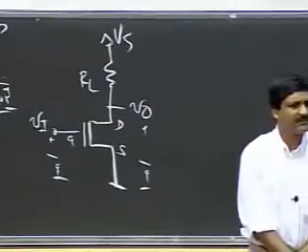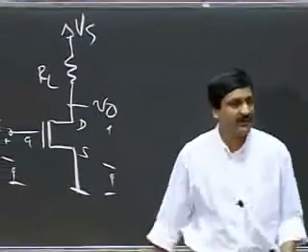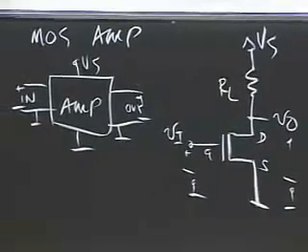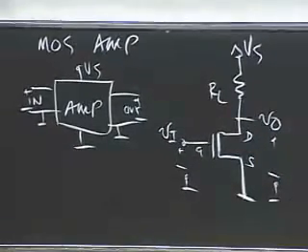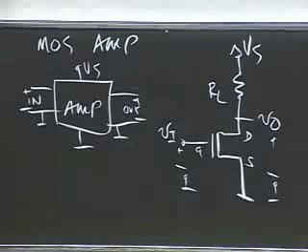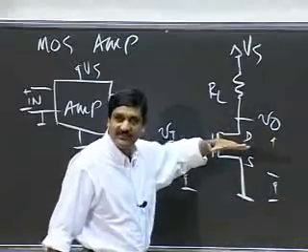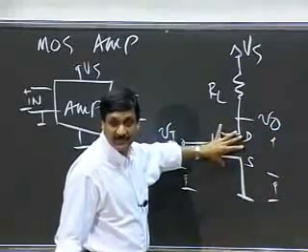So what's different here? We showed you the circuit as an inverter. What's different here is that when we look at MOSFET behavior as a current source, this behaves like an amplifier. When VDS is greater than some value, then this behaves like a current source.